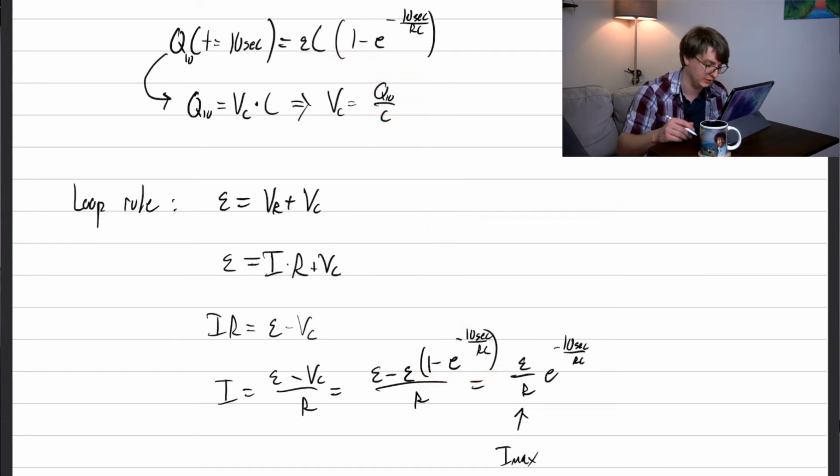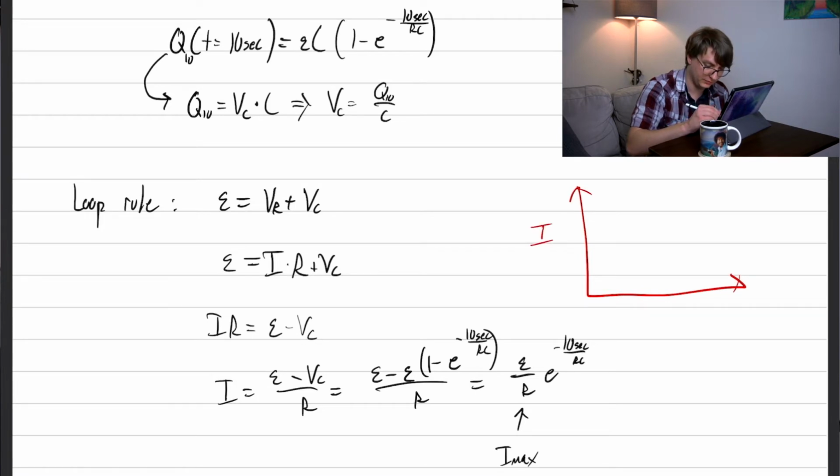And it's a little bit of a complicated expression, but some interesting stuff happens. So this one term gets canceled out here. It gets subtracted off when I distribute this epsilon into the rest of the equation. So all I'm left with is essentially V equals IR in a kind of way, with this functional dependence on time, this exponential decay. So if it was at the current maximum, this thing would just be 1, and we would just get V equals IR. That's really what this is saying. But I have this component that's exponentially decaying over time. So what does that mean? If I draw a graph of the current over time, this is time. It's at some maximum here, given by V equals IR, and then it's exponentially decaying to 0.